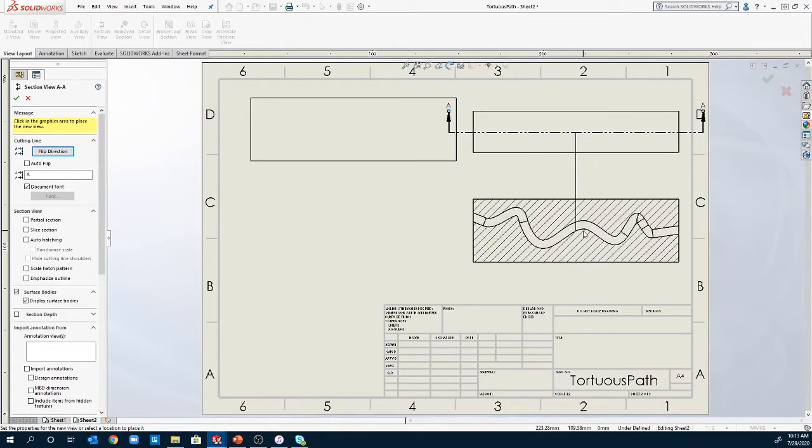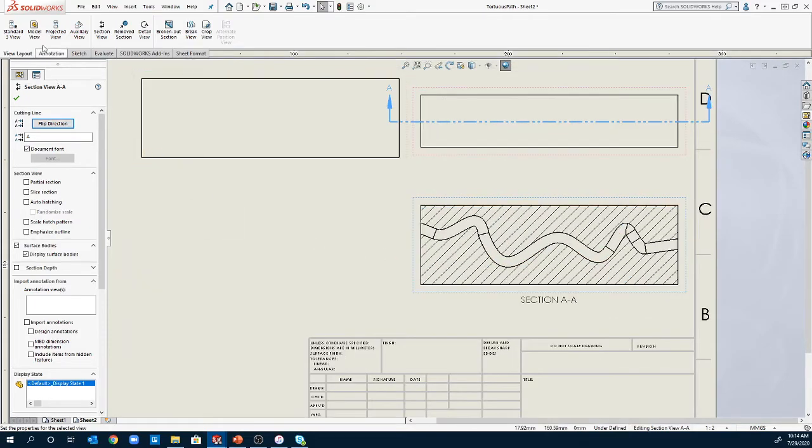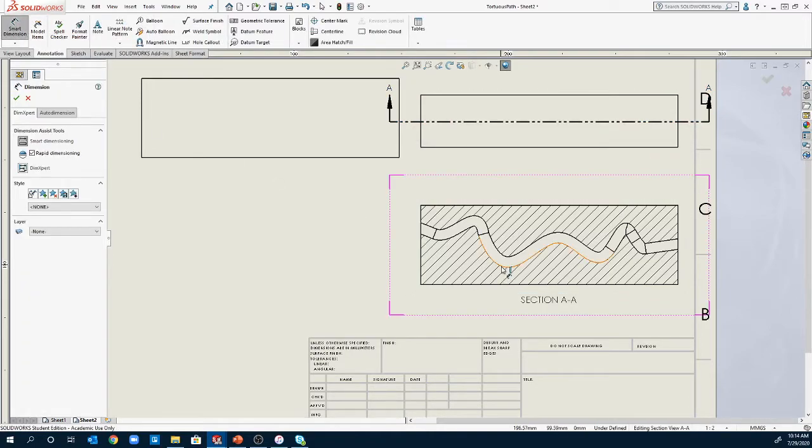And what that's going to do is give us a new drawing which contains the information that's along this line. So that's as if we just did our section and cut our part in half. Now the grayed in, the hash marks are notating where there's material, and the white is where there's none. So this allows us to see inside the part. We can also then go in and use things like our smart dimension to get things like curvatures and distances and all of those sort of things that become really, really important as we continue forward.